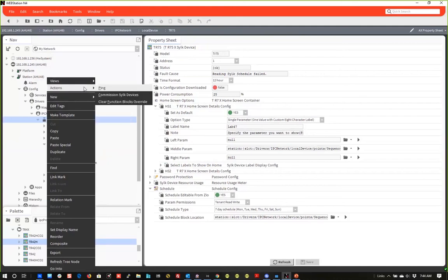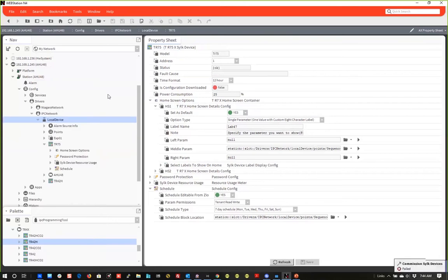Once you finish your configuration of your ZIOs, you'll do a commission. Now, I'm not even sure if I have my addressing correct, but we'll see what happens when I do that. Okay, so it did fail. Let's see. Oh, they're both set for address 1. That's why. Is it the dip switch on the back that does it? Don't you have a way to do it from the front? No? All right, I put that together last night, so I obviously fell down on that task, so I can actually do it.